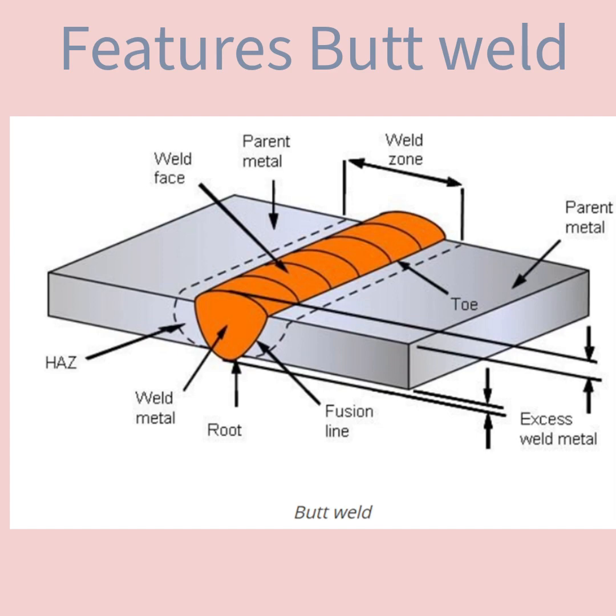This is a very important feature of a weld since toes are points of high stress concentration and often are initiation points for different types of cracks, for example, fatigue and cold cracks. To reduce the stress concentration, toes must blend smoothly into the parent metal surfaces. Next, excess weld metal is the weld metal lying outside the plane joining the toes. Other non-standard terms for these features are reinforcement and overfill.